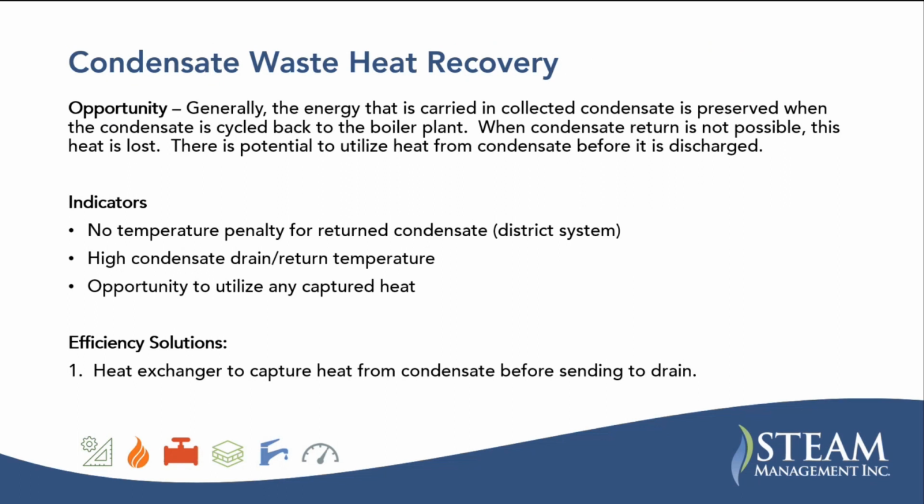Condensate waste heat recovery. Generally, we've talked about how the energy that's carried in the condensate is preserved when the condensate is cycled back to the boiler plant. When condensate return is not possible, the heat is lost. There are also situations where the user is on district steam and they are incentivized to use as much of the energy from the steam that they're paying for as possible before they send it back to the district plant. So even once they get down to condensate, if they have no temperature penalty for the returned condensate, they want to get as much energy out of that as possible. So that's another situation where you're trying to get heat out of your condensate.